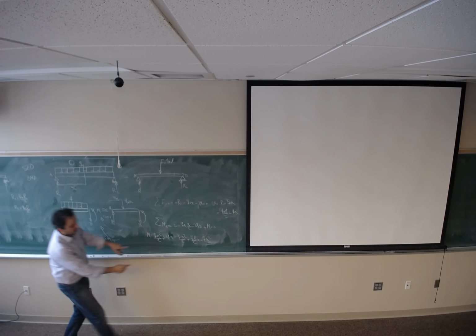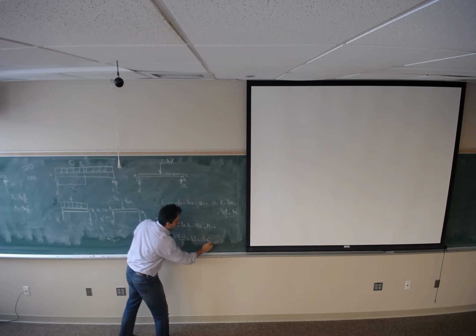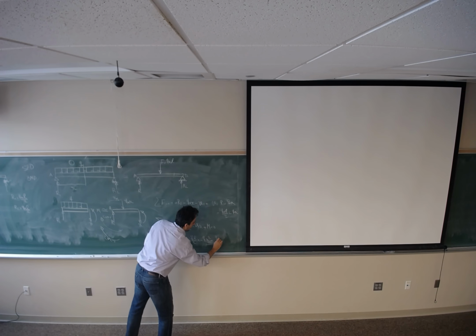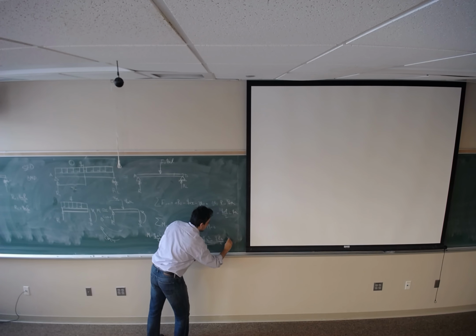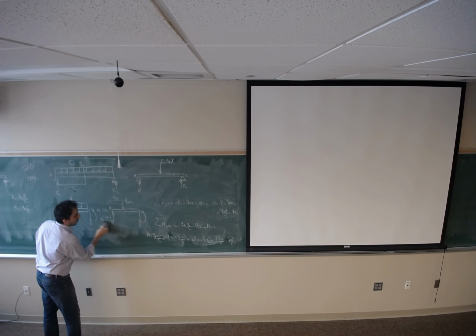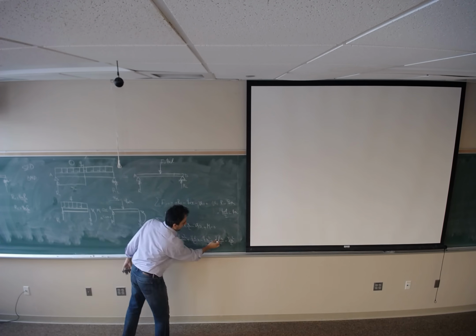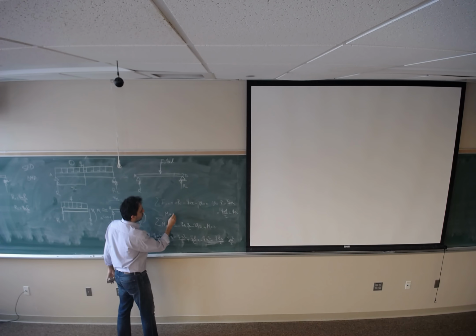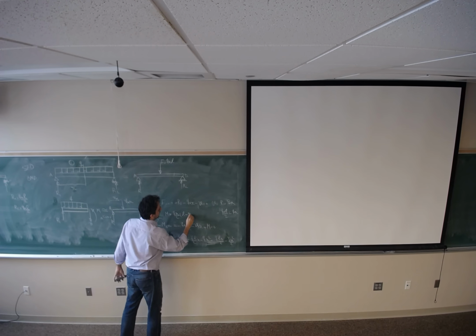I have negative Qx squared, positive Qx squared divided by 2. I will get QLX divided by 2 minus Qx squared divided by 2. Or I can say M would be, just take Qx divided by 2, times L minus X.